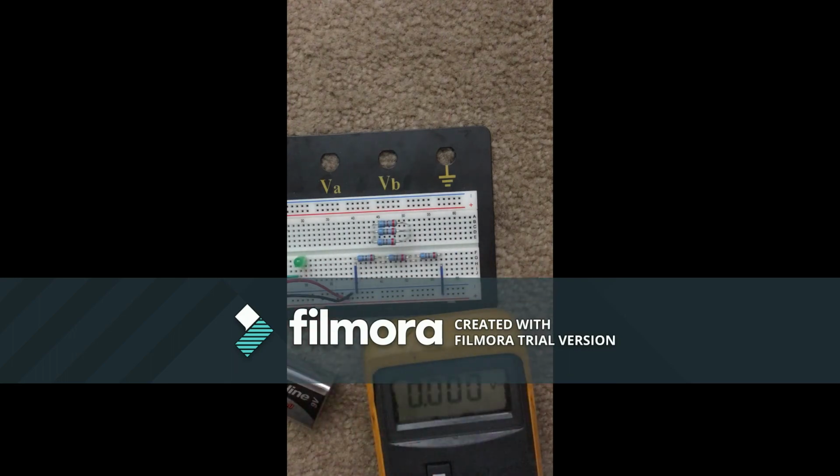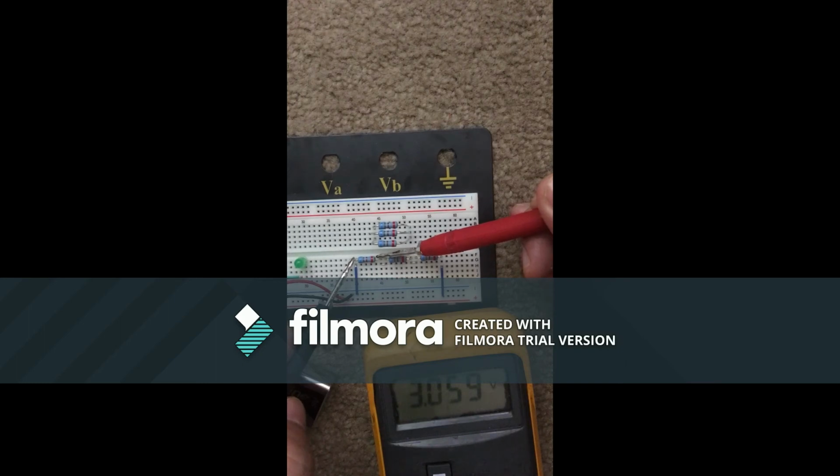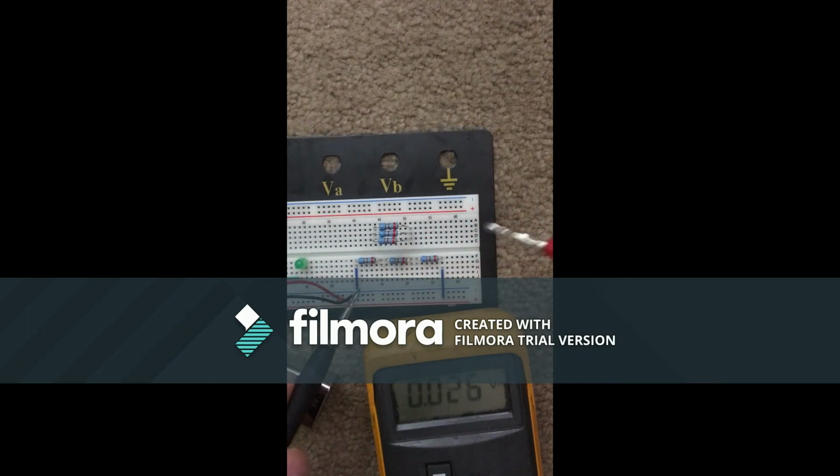Okay, so for the first resistor, we have a voltage drop of 3 volts. Second resistor, we have a voltage drop of 3, and the last, we have a voltage drop of 3. So the total of this should provide us 9 volts. Again, each resistor provides a voltage drop of 3 volts. That's for R1, and for R2, 3 volts as well. For R3, it's 3 volts.